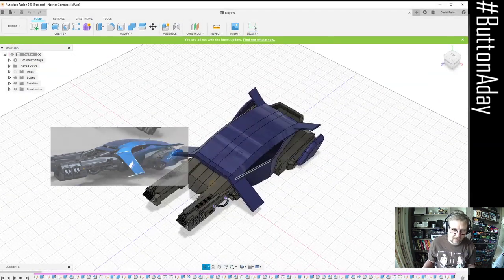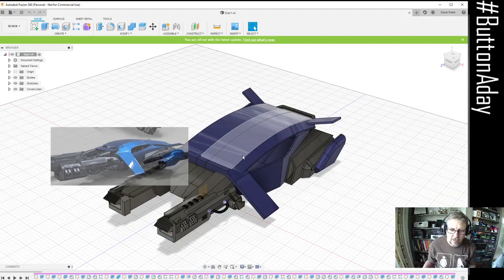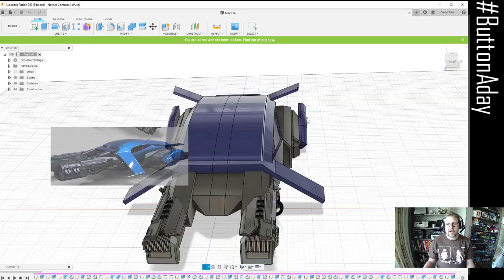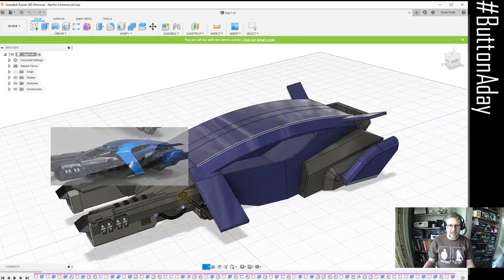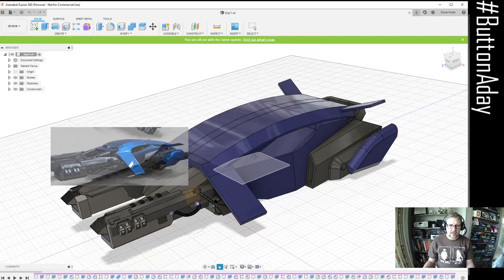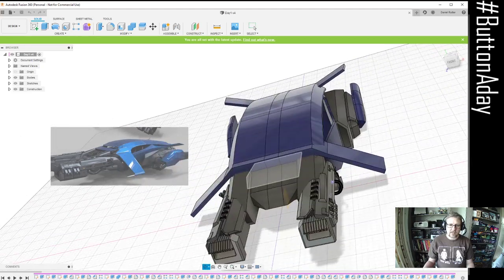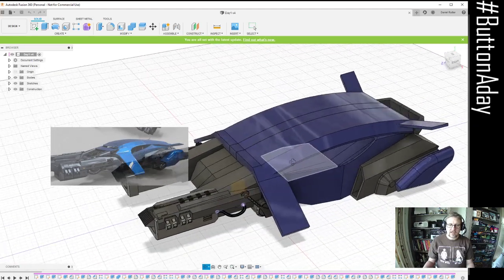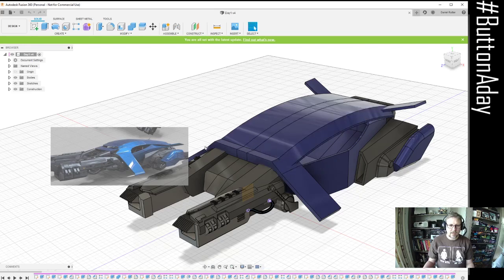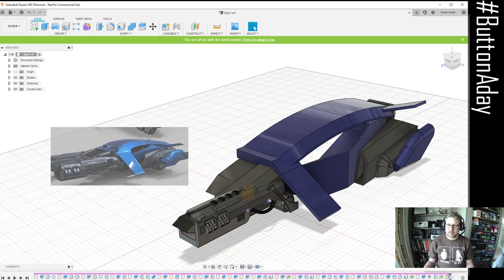Once that's finished messing around, we're going to look at this roof section, which we kind of blocked out yesterday. We've got a rough idea of what's going on, but we're going to try and model something a little bit nicer today. Again, we're just going to work on half a roof and then mirror it across. So we're going to go to our feature tree down the bottom, navigate to the very end of it, and wind back on our mirror feature.